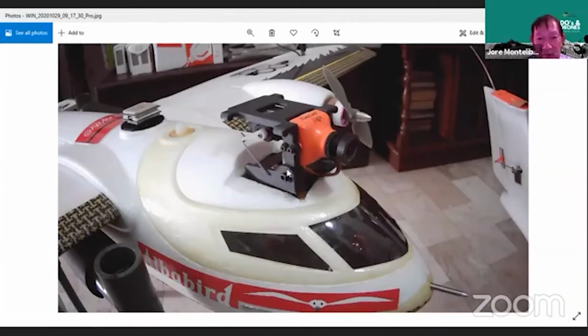We usually call this type of drone operation FPV, or first person view, because what the operator will be seeing in the monitor on the ground is what the camera is looking at. This is very similar to what you see when you operate a DJI multicopter. The only disadvantage of this drone in that kind of operation is that it cannot hover. So you cannot stop the drone from flying. It just goes on and on. But the advantage is that it can cover a longer distance. The actual performance of this type of plane in other countries is that it has been able to reach 200 kilometers distance. That's a lot of distance you can cover.